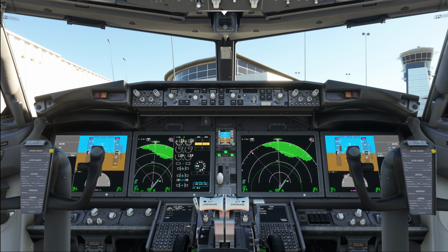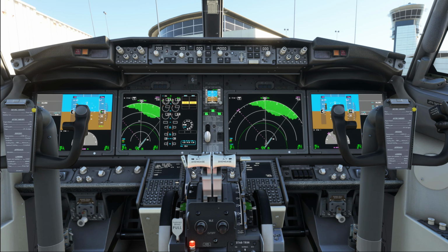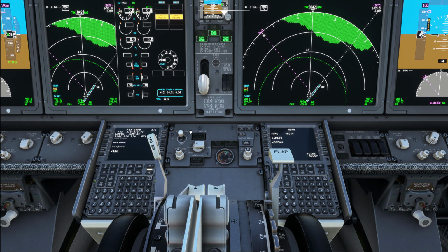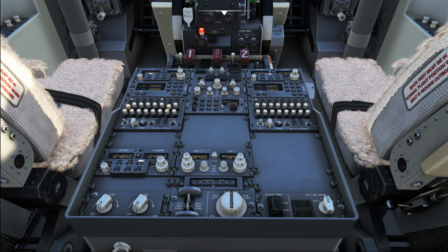Once we're done with that, we're going to do the same on the aircraft's main panel, going over here, going down here, onto the panel in between the FMCs, and last but not least, we are also going to go over the pedestal, again top to bottom, left to right. That way, you have an organized scan flow, and it is much easier to remember everything that you have to do. So let's go ahead and start on the overhead panel on the top left.